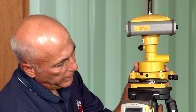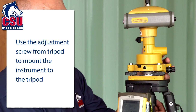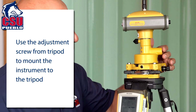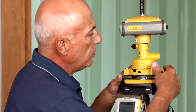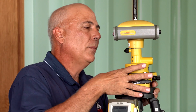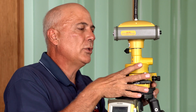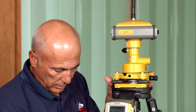The tribrach is mounted to the tripod, and similar to all of the other equipment, it has an optical plumb with which we can set up directly over a point. We would also use the leveling screws to make sure that the instrument is level and directly over the point for which we have the known data.